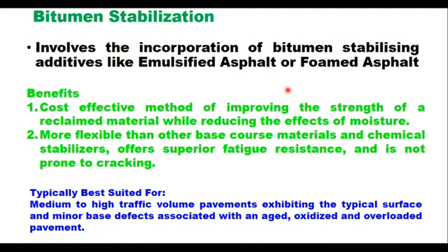It offers superior fatigue characteristics and is not prone to cracking. And it is typically best suited for medium to high traffic volume pavements exhibiting the typical surface and minor base defects associated with aged, oxidized and overloaded pavements.